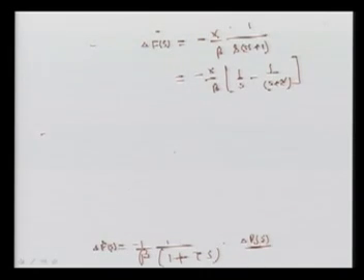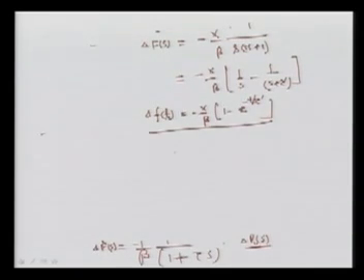To go for the change in frequency in the time domain, we take the Laplace inverse, and then we get minus X upon beta, 1 minus e to the power minus t upon tau prime. So this is your first order equation in the time domain, because we had only one transfer function and that is a one order transfer function. So this is the time domain response of this loop.